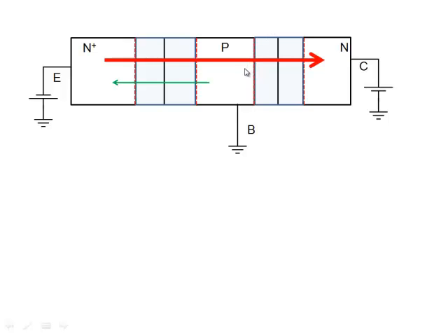Now, why does a small current flow across a reverse bias junction? The reason is that we have very few electrons here. So the bottleneck to current flow is not that I have a small electric field here. That's not the bottleneck. Less current flows in a reverse bias junction because I have very few electrons here, right? And therefore, if I increase the electric field here, it doesn't do much to my current. Whatever electrons reach here, they anyway get collected here.